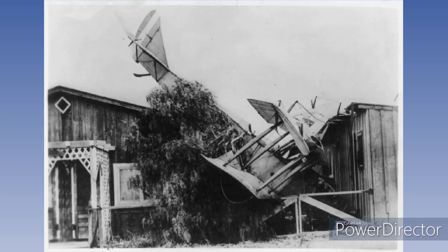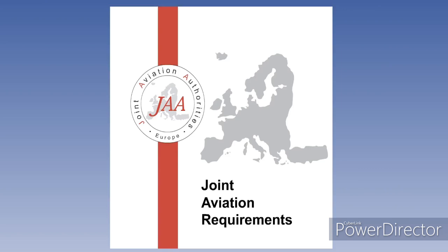You'll be taught how to do this during your flying training, but these lessons will give you the theoretical knowledge you will need to understand how and why stalls happen. Different types of aircraft exhibit different stalling characteristics, some less desirable than others, but all should give the pilot some indication of an incipient stall. Airworthiness authorities specify the minimum stall qualities that an aircraft must possess. Reference will be made in the course of the lessons to such regulations for training purposes, but you should note that these requirements are occasionally subject to change.